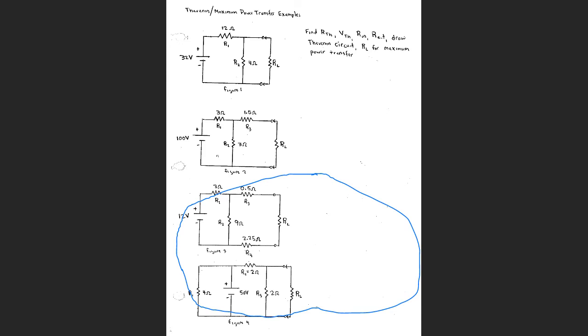It doesn't know anything about R3. So it sees 3 ohms of opposition and another 3 ohms of opposition, 6. It sees an input resistance or total resistance or equivalent resistance, whatever you want to call it. The resistance the battery thinks it's hooked to, the total resistance of the circuit, is 6 ohms.